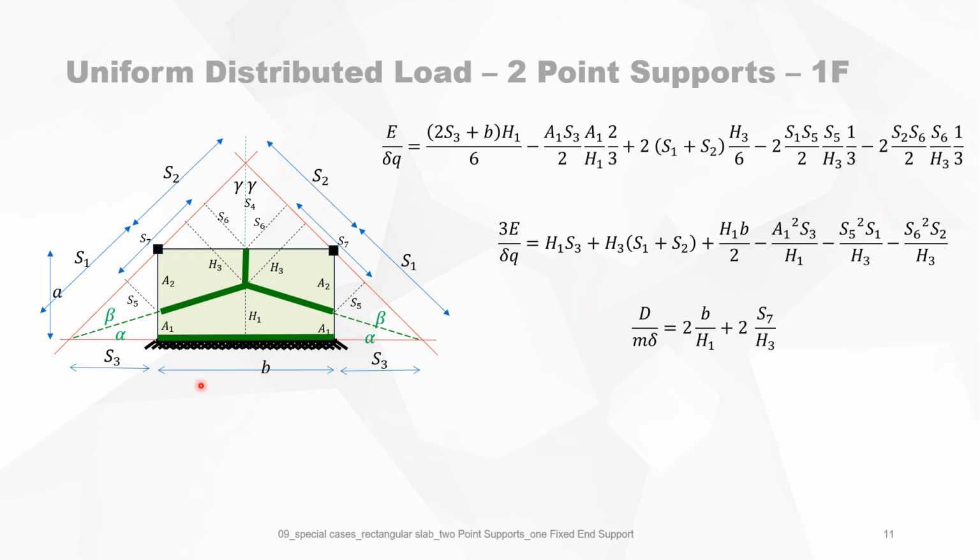The work done by the internal forces is then this yield line projected around this axis of rotation gives you B times the angle of rotation delta divided by H1. So that's this one. The negative bending moment gives you the same. It's projected on this axis of rotation, so it's B, and the angle of rotation is delta over H1.